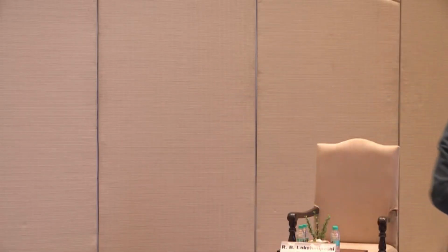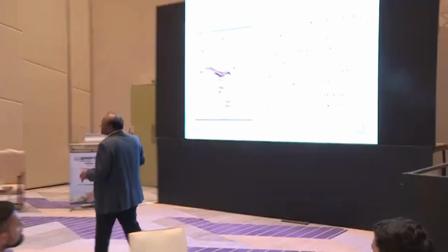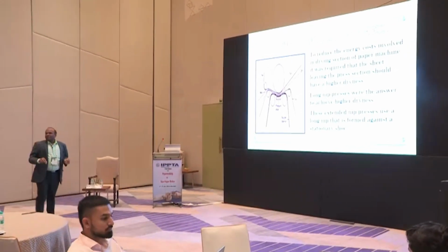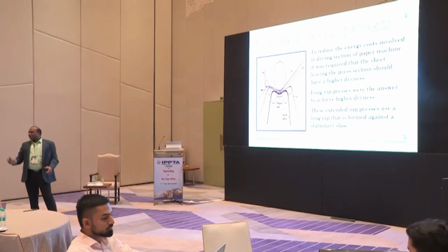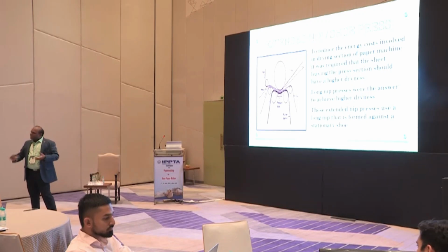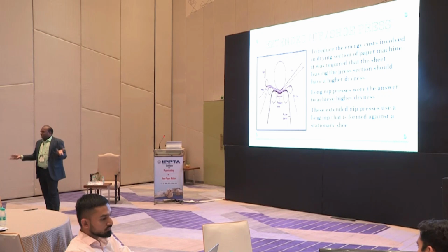One among the important press parts is this one, the extended nip press, otherwise we can call it a shoe press, similar to the retrofit and hybrid formers we discussed now. Similarly, the latest machines will be equipped with this kind of press part. Here, as we already discussed, two important factors are the nip load and the dwell time. At any cost we could not increase the nip load further. Can we squeeze a cloth to more than one extent? We can't. Whatever we can squeeze, that's all.